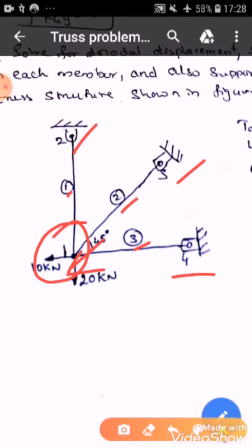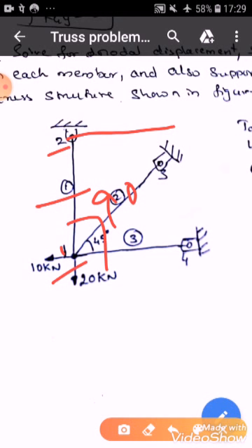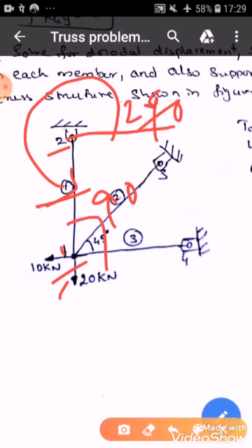And just to check the angle made by element 1, if you are connecting between 1 and 2, then the angle made by it will be 90 degrees. And if at all you think of some other values, see here, element 1 is connected between 2 and 1. So why should I follow only what sir does? I'll follow something else. If you want to take element 1 connected between 2 and then 1, that is, local node 1 will be 2 and local node 2 will be 1. In that case your angle theta will be 270 degrees, my dear friend. That's the only change.